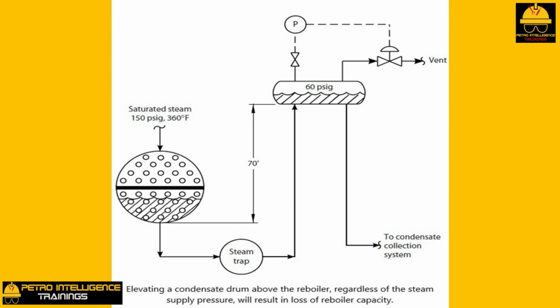The required subcooling may easily flood half or more of the surface area of the reboiler. The loss of reboiler capacity typically will not be tolerated by the plant operators, who will then be forced to drain the valuable steam condensate to the sewer.